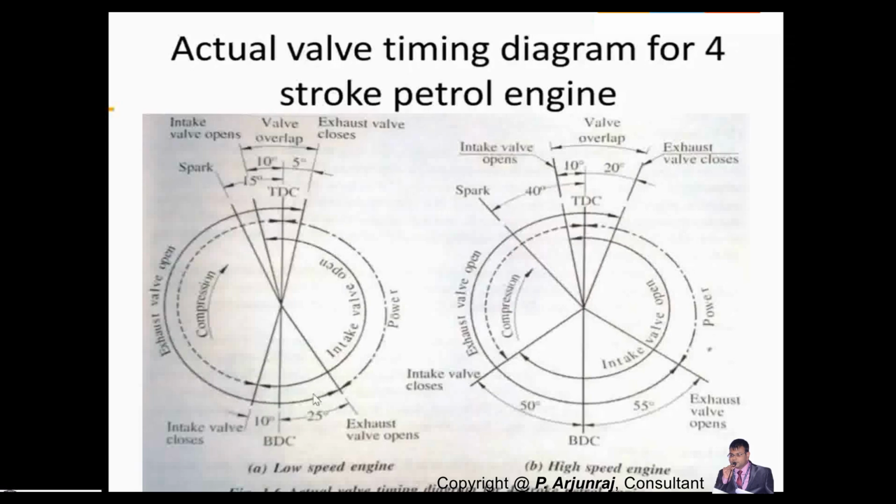When the piston moves from TDC to BDC, because of the gasoline engine, the air fuel mixture comes in. This is in the case of the theoretical valve timing diagram, where we normally say the fuel air mixture comes in through the inlet valve at the TDC position.